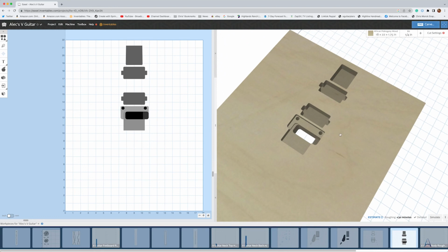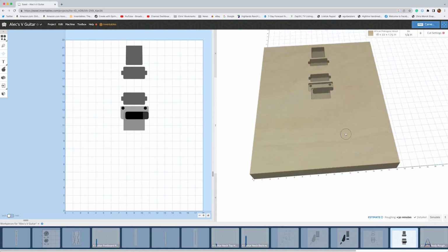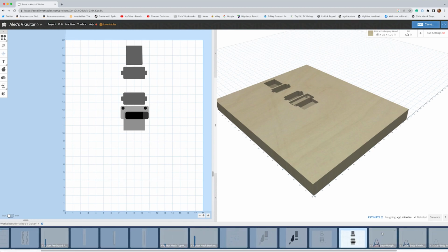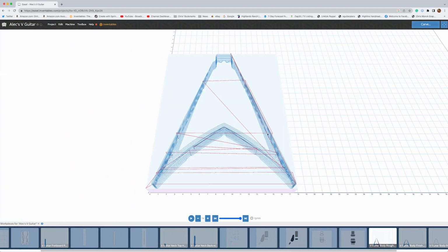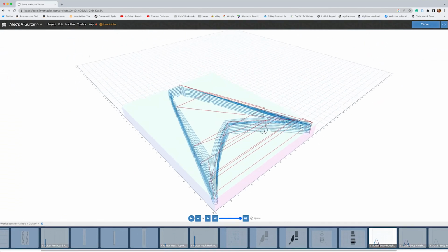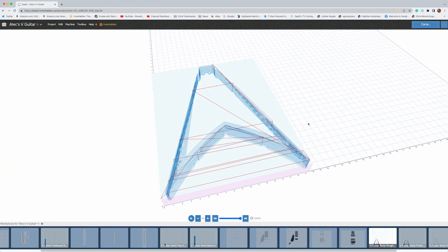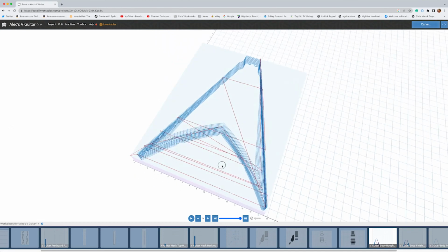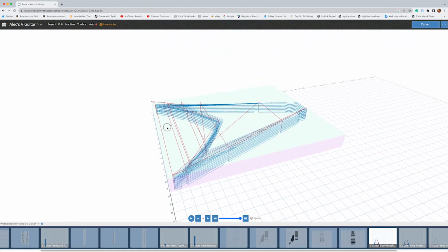And then once that's done, again, the spindle will return to that lower left corner, and I'm going to swap out for, probably for this operation, a 1/4 inch diameter upcut bit, just like I used on the pockets, but it's going to be a taller bit because I'm going to be cutting through the full thickness of that blank. So I need a longer reaching bit.